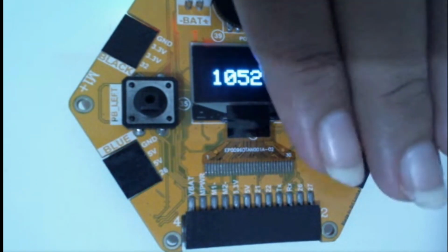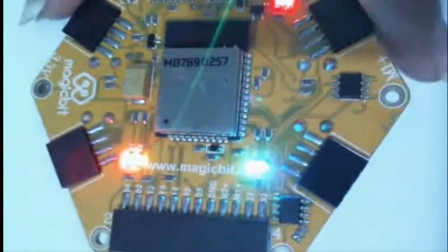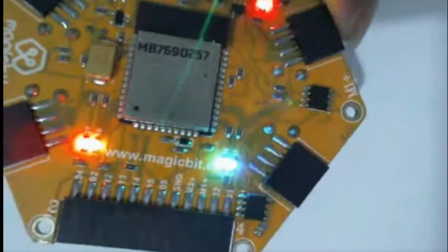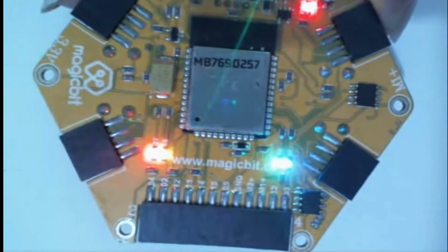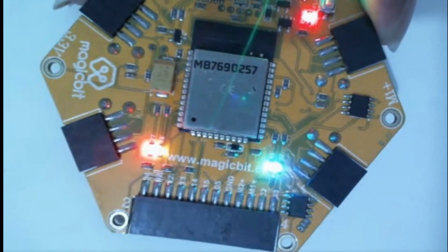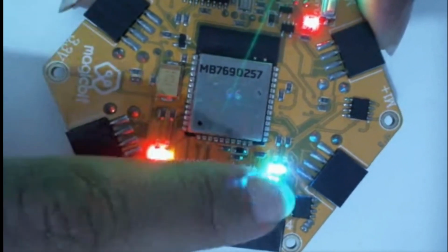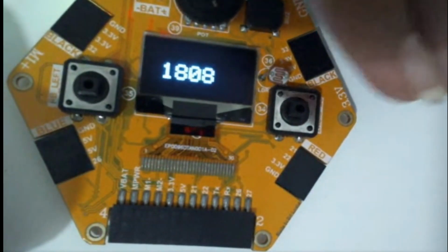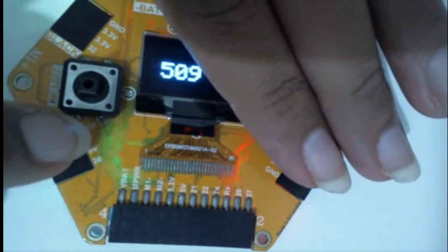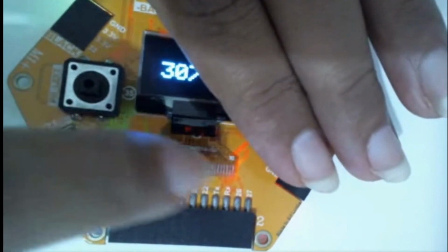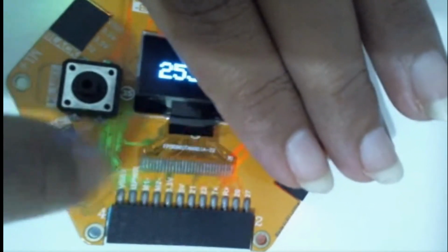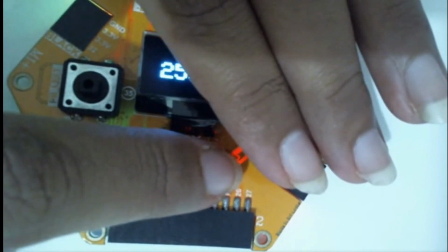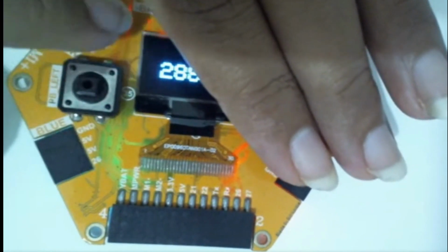And if you check the other side of the Magicbit, I will turn it back. See, now the LDR is facing downward. So automatically the amount of light detected by the LDR is below the value we gave. So as the condition is satisfied, you will see all the 4 LEDs lighting up, right? Without turning to the other side also, you can check the output. If the value of the LDR is below the given value, you can see some light flashes or light through these spaces in the Magicbit. So there also you can check both the output from the LEDs and the output on the display, right?